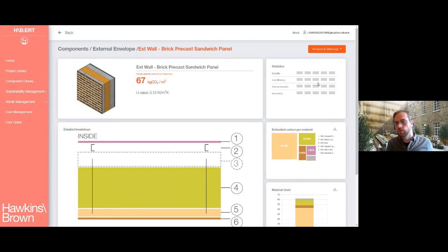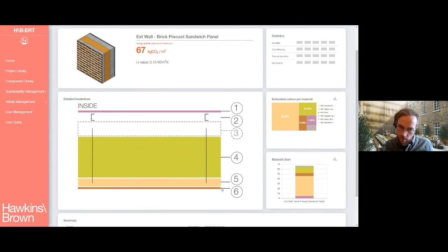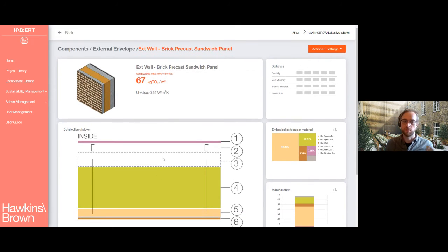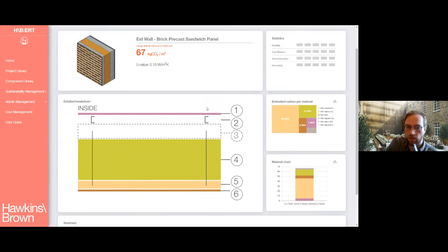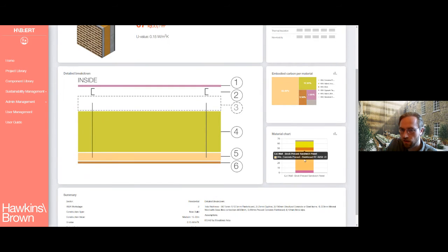So this is what we have. These are our standard wall build-ups that we now have in Revit that we give to our teams. And there's a whole lot of learning gone into this. So there's a U value, there's a fire retardance level, there's air tightness levels. We know a lot about these systems. We know what they can achieve, and we are also then able to create the right kind of Revit materials and elements so that they export an accurate impact of the total embodied carbon.